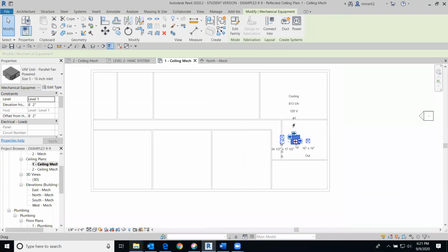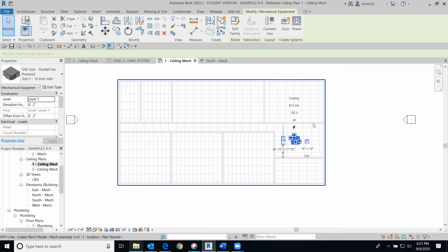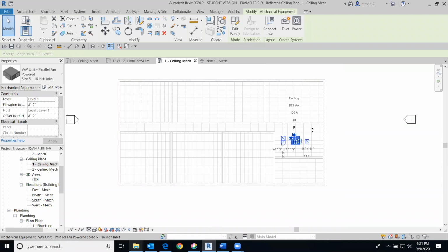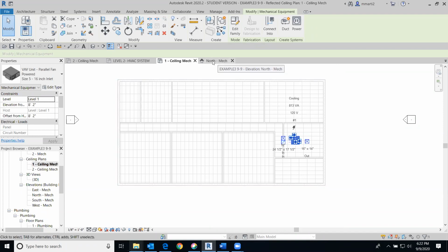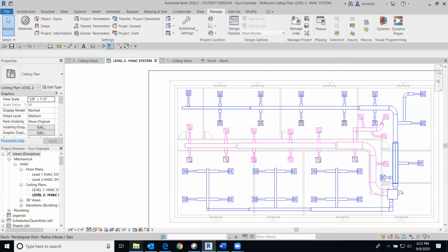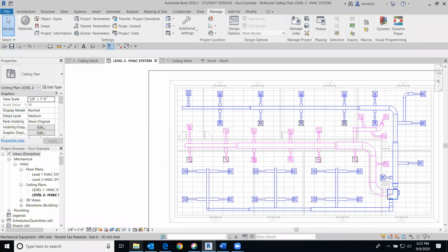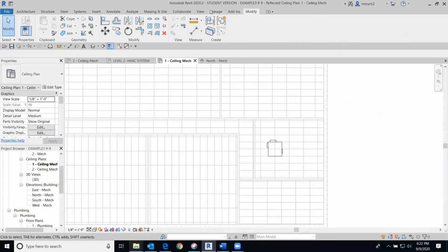Now, the biggest thing that we will need to think about is the way that these vents are going to be running. We don't have a lot of space vertically in the plenum to really have these vents cross one another, which is why in this drawing right here, the return handler was actually rotated in order to make our ductwork flow a little bit better.